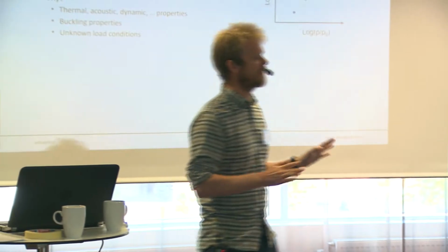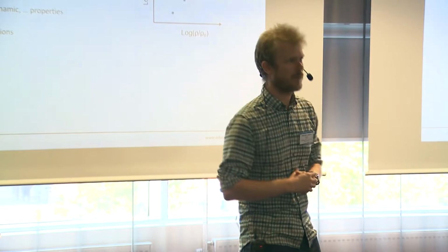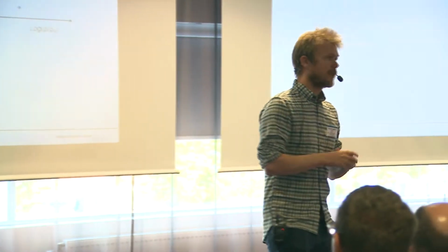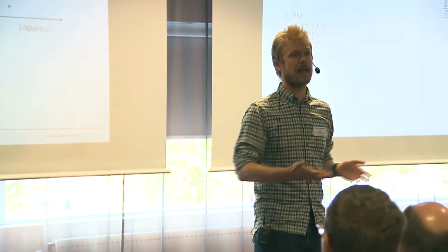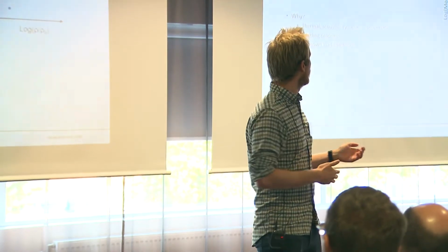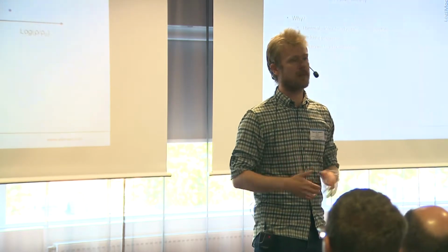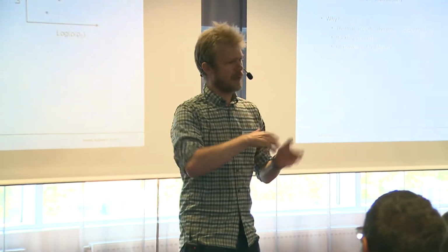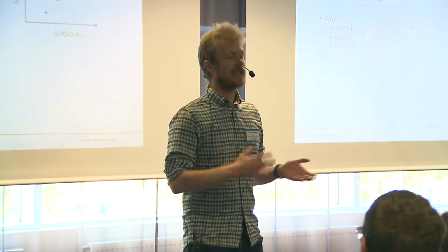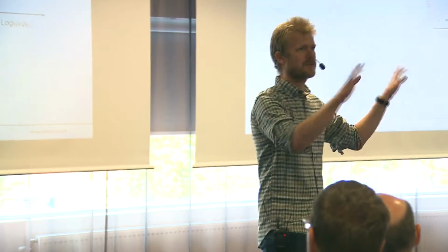And luckily it turns out there are plenty of reasons to do this. It's just not your typical stronger argument that you hear. So you might want lattice structures because of thermal properties or because of acoustic or dynamic properties in the lattice. One thing I'll get back to is that lattice structures have superior buckling performance, so we'll get back to buckling in a moment. And also, if you're not really sure about what load my part is going to sustain, then lattice structures can also be a good compromise, because they can distribute loads throughout the lattice structure, and we'll get back to this in more detail as well.